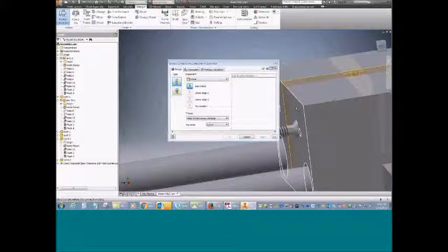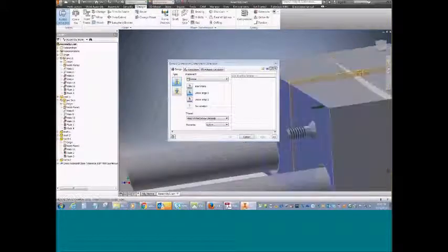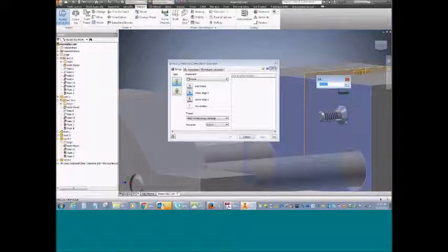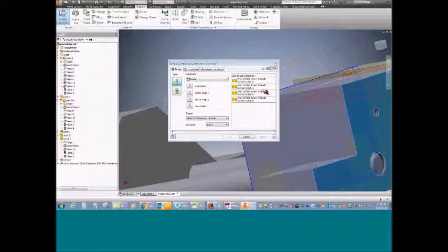But basically I can pick where I want to start my bolted connection. I need a linear edge. So we'll just go there, some distance, there, some distance. Pick my termination. And then it puts holes in all the parts, and I can add fasteners that go in those holes. So that does everything at once for you. Puts the holes in for the fasteners, and then puts the fasteners in themselves.